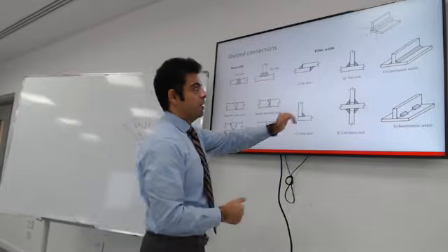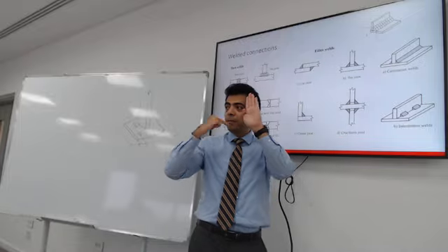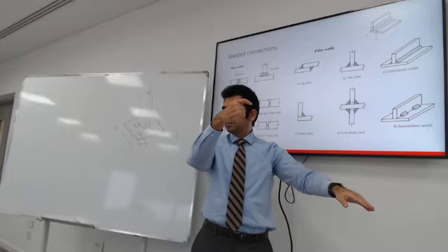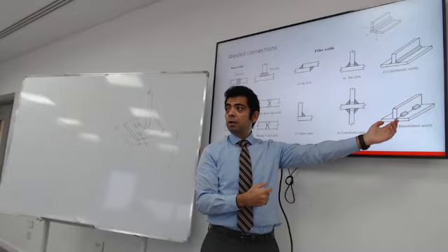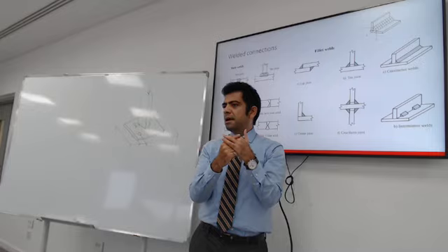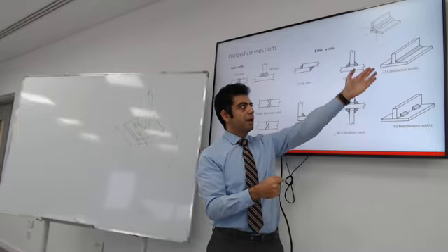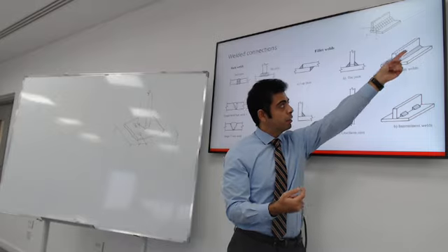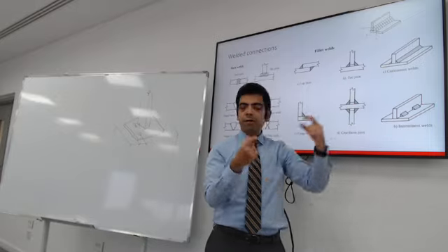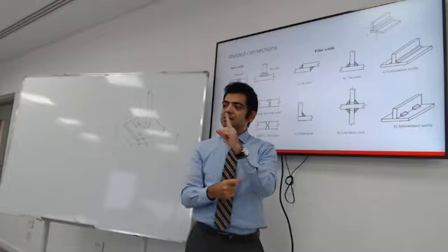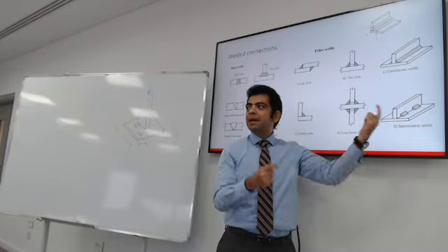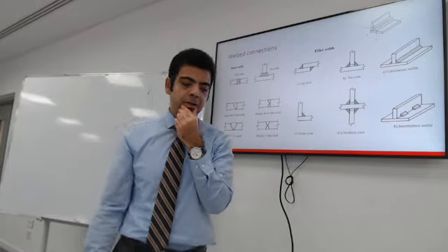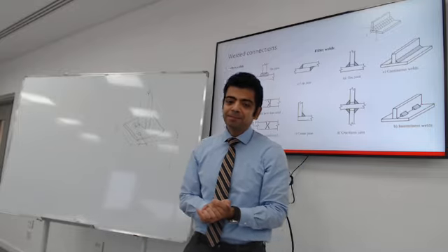You can have a continuous weld. You can weld something continuously, or you can have an intermittent weld, or stitch weld, if you will. That works as well. You can save time. It's not going to cost that much. And it depends on the capacity that you're trying to get from that connection. If you don't need all that length of weld, you can divide it into shorter sides. Having said that, there is a minimum length. You can't make a stitch weld shorter than a certain length. And the code will always give us instructions, or guidance really, on things like that.